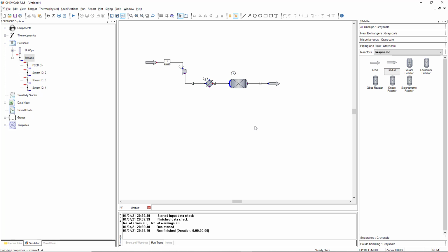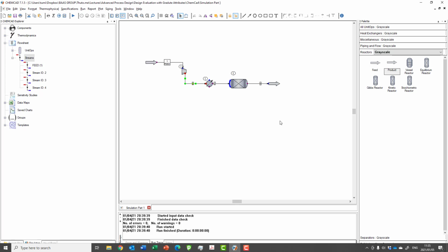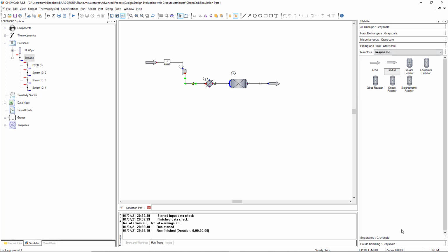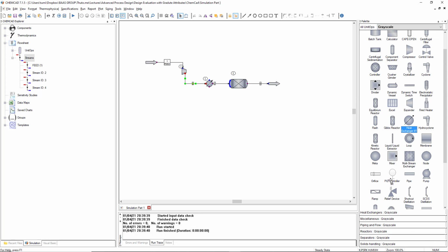We can exploit this high pressure energy to drive the movement of the fluid from the reactor to the distillation column, instead of using the pump. However, this pressure is very high and needs to be reduced to about 5 bar before we can prepare to send it to a heat exchanger and then, to overcome the momentum work and piping friction losses as we transfer the stream to the distillation column. Let us now add a valve to reduce the pressure from 50 bar to 5 bar.